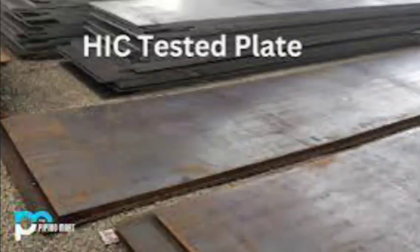Now, for NACE material, what is the restriction? Basically, they restrict the chemistry to 1% nickel, hardness to 22 HRC, and sulfur content. They say it should not be a free machining steel, it should not have a higher sulfur content, and the sulfur content is also restricted. They have a lot of other restrictions, like if you have cold work, you need to do PWHT. For welds, you need to control hardness, or otherwise bring it down to 250 HV by doing PWHT. So there are a lot of restrictions given in Part 2.